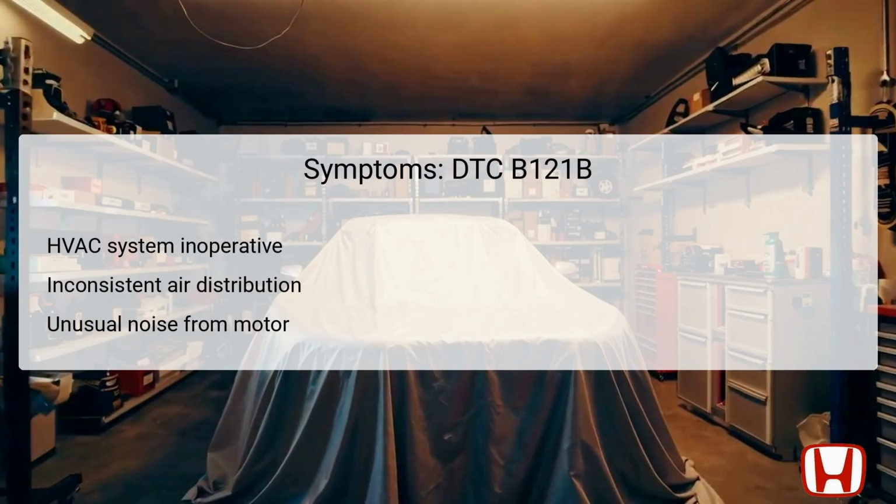Another telltale sign could be unusual noises emanating from the mode control motor itself. If the motor has sustained internal damage, it may produce grinding or clicking sounds, representing an underlying mechanical issue. Recognizing and correlating these signs with the diagnosis of DTC B121B is crucial for effective troubleshooting.